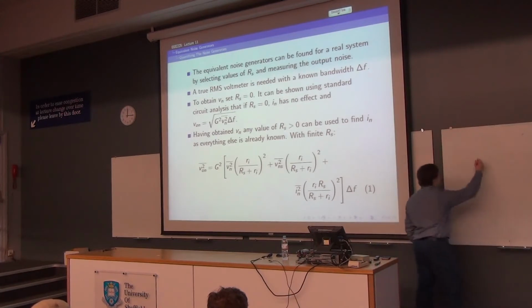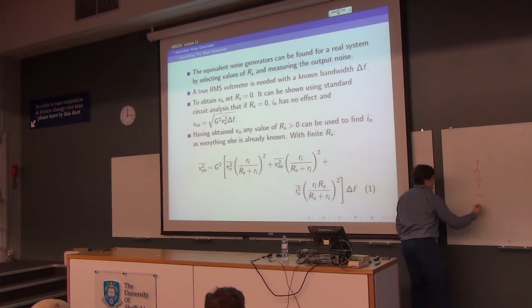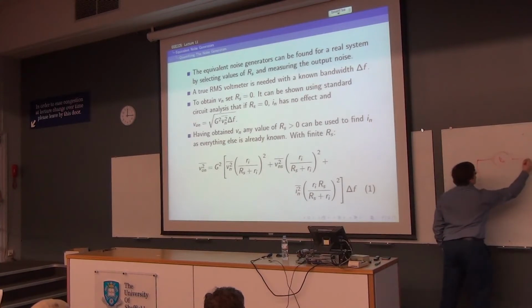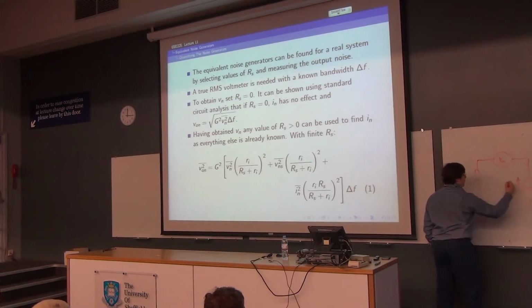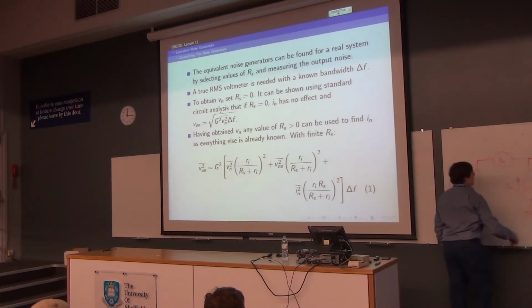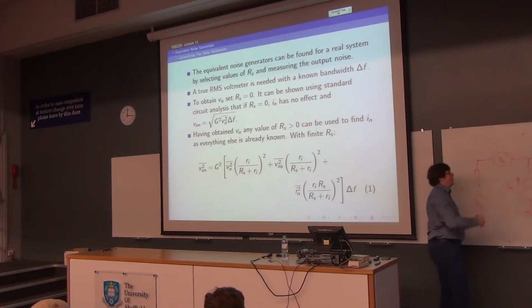So we had source resistance, this is VNS, that's the ground, then we got Vn, then we got In, and then our output VON. I've made Ri infinite, so it's gone away.